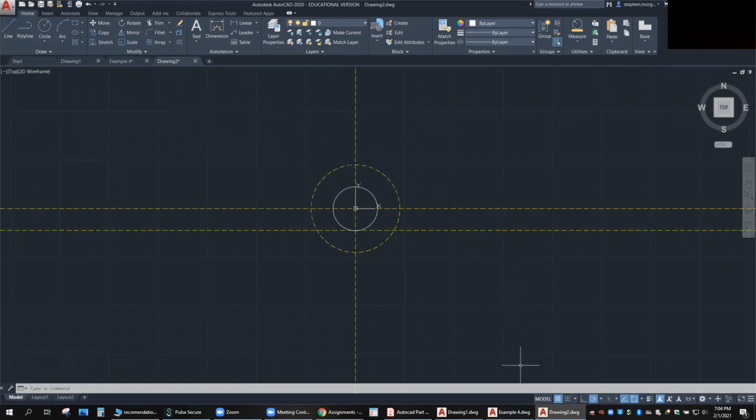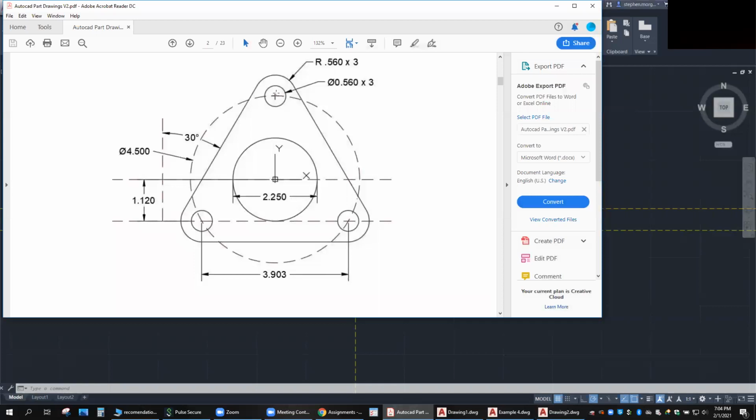All right, so here's another thing that we're going to do in terms of laying this out. We've got a circle here, and then we've got an outer radius out here. This outer radius actually shares a center point with this inner circle. So we're going to draw these not as radiuses, but as actual circles around those. We'll have an inner circle and an outer circle, and then we can connect with lines between those outer circles and get the perimeter of our part.